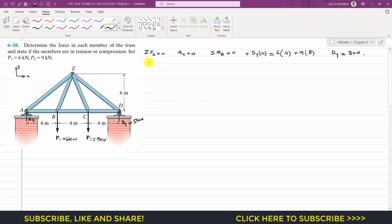Now if we apply the summation of forces along y-axis equals 0. So AY is acting in the positive y, so I will write plus AY. P1 and P2 are acting in the downward direction, that is in the negative y, so we will subtract them. So minus 6 minus 9 and plus DY. DY is acting in the positive y direction, so I will write 8, and this is equal to 0.